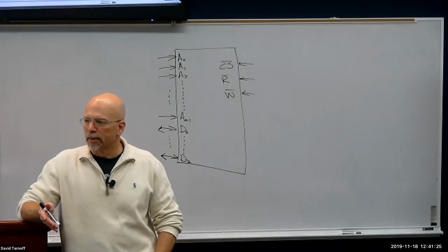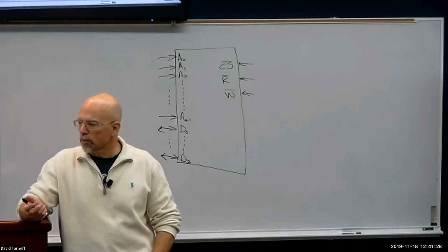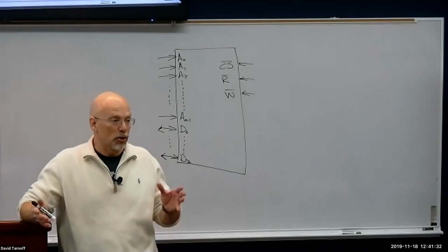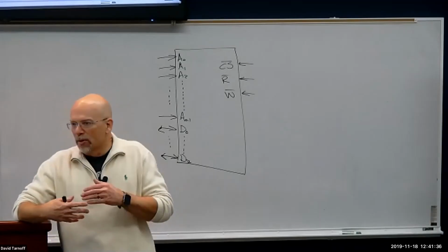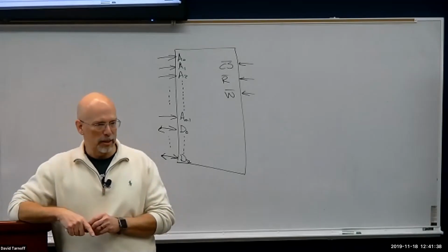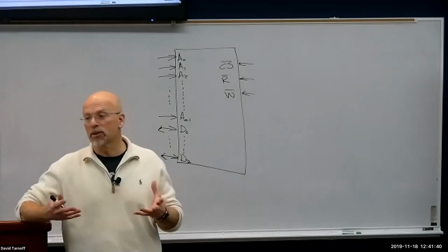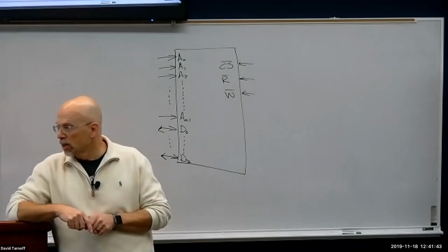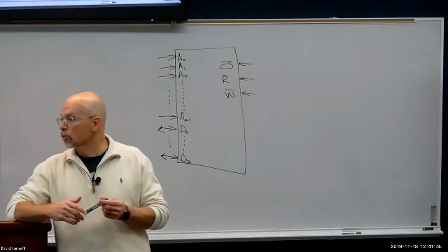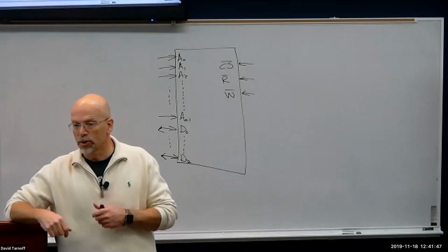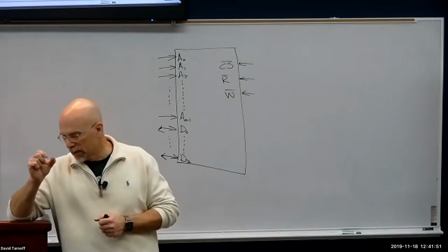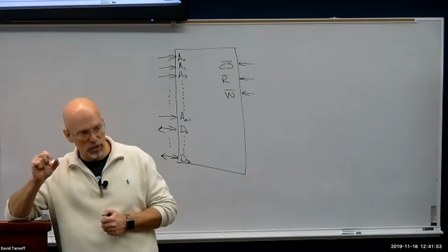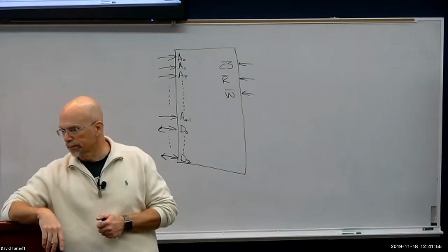In addition, as we start to get devices that are smaller and smaller, the more connections we've got, the larger the chip has to be in order to support all those connections, and the more board space you've got to take up. In addition, chips that have more pins also are more expensive, because that's one of the high cost portions of manufacturing ICs, actually connecting the signals that are on the silicon to the outside world.